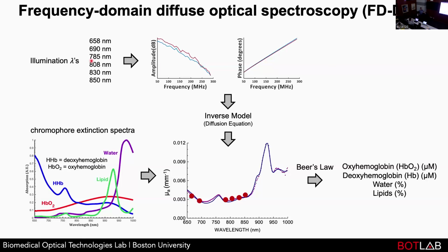So really what you need practically is to measure for long enough that you can get several periods of the cycle that you would need to do, say, a Fourier transform to calculate the amplitude and phase. So the measurement length, and this would be an analog to digital converter, your measurement length or number of samples for an analog to digital converter has to be enough to meet the Nyquist criteria in order to get the amplitude and phase measurement. Yeah, that makes sense. Great questions. Any other questions?